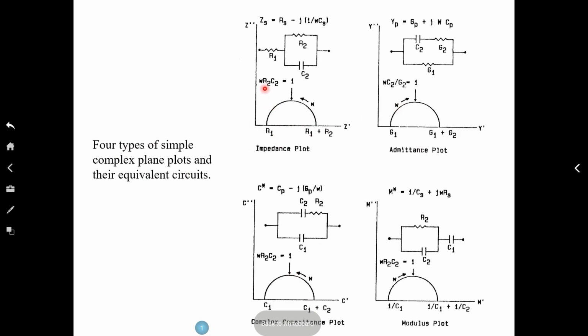Depending on what plane they are in, so this is the impedance plane. That's your RC parallel connected with a series element that we have done. If you see this in an impedance plane plot, the circuit would be a completely different combination of circuit elements. Still capacitance, this is now conductance, which is 1 over R. Okay, this is conductance. If you see this in the capacitance plane, the same shape transfer. Look at the circuit, right? Very different.